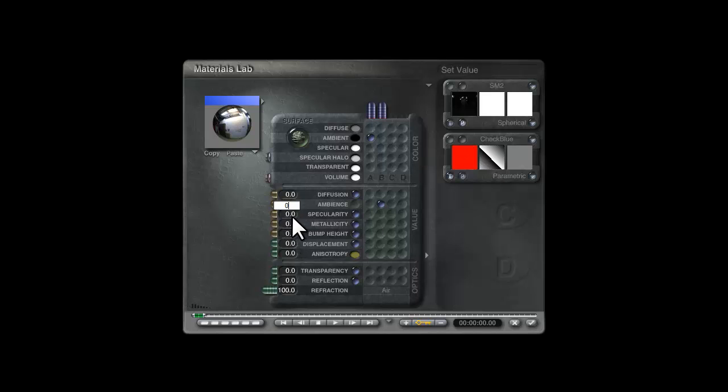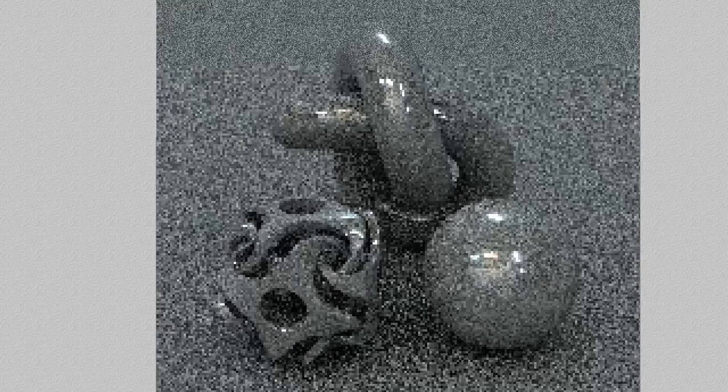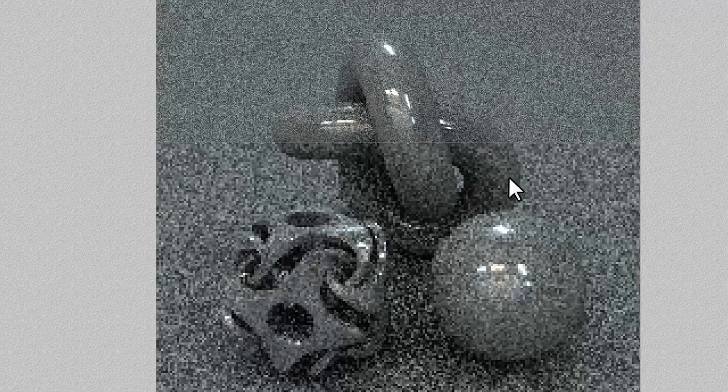I'll try a lower value, so maybe it'll just pick up the fluorescent lights better. And the export options of Bryce. So I really like this idea because it uses so many of Bryce's features, the things that it's got an advantage on. So what I'm going to do now is make sure that the background isn't in shot, so we're only dealing with the reflections. And you can see that the ground's fairly even. Remember, we're looking for a fairly diffuse lighting.